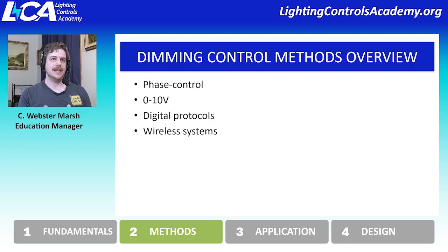And also something to keep in mind here is that in our industry, we like to use the term protocol to cover all of these different terms, but really it's only when we get to the digital level that we're really communicating using a protocol, which is a structured definition for how communication is going to work on a system. Whereas when we're talking about 0 to 10 volt and phase control, it's an analog communication method. It's not a protocol, but we just like to lump everything together.